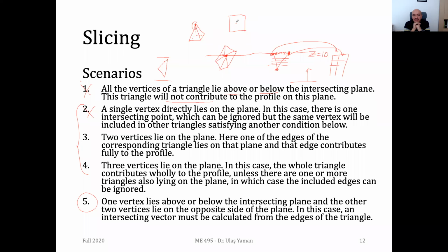No. We don't need to store it actually, since our printer cannot print a point, obviously, a single point. That will be highly difficult, and at least we need to have, maybe I'm drawing it from the front view. It's better we stop it somewhere here. Since having a sharp corner is not possible in additive manufacturing. We will always have kind of a radius there. It's not possible even in that type of additive manufacturing or stereolithography. It will be quite difficult. We will not have a very sharp point there due to the nature of our, let's say, additive manufacturing.